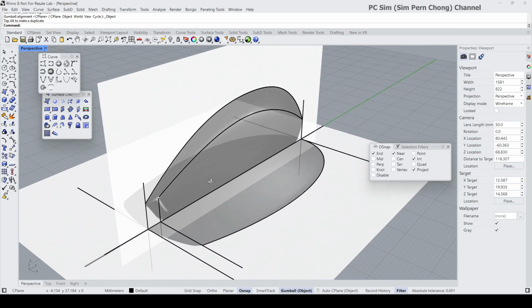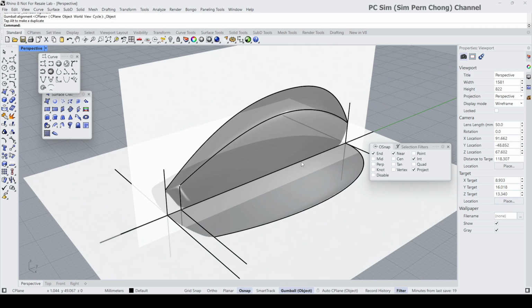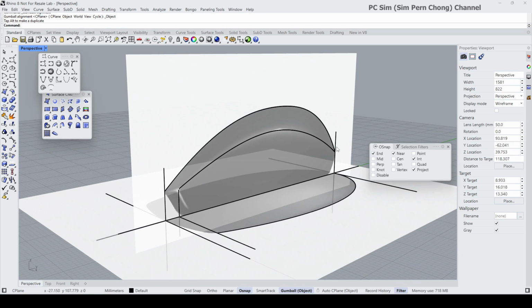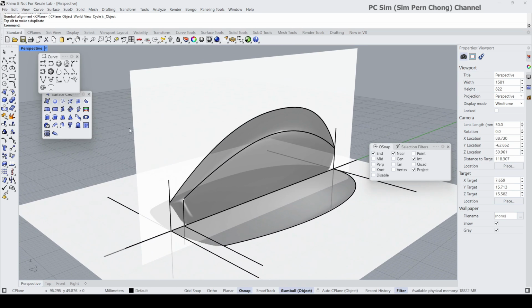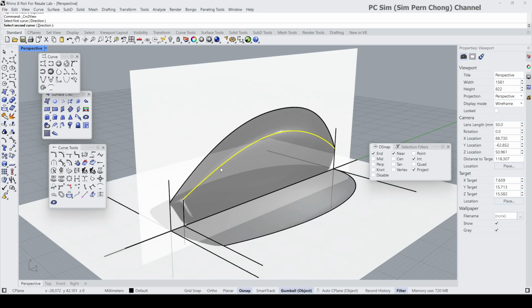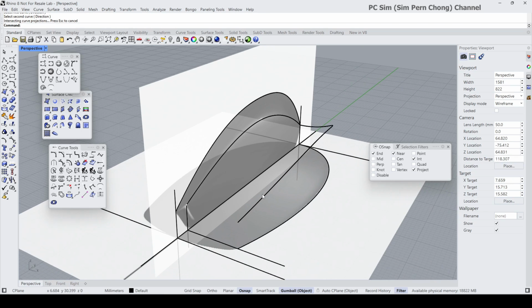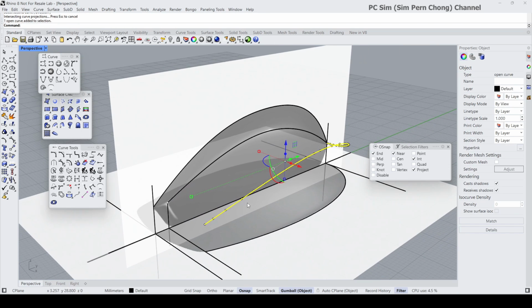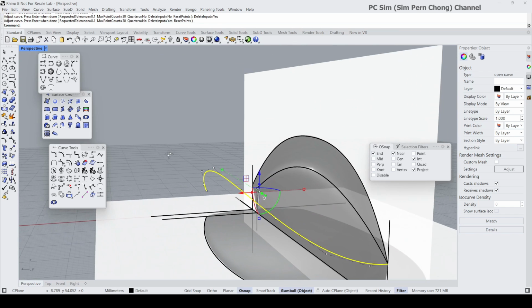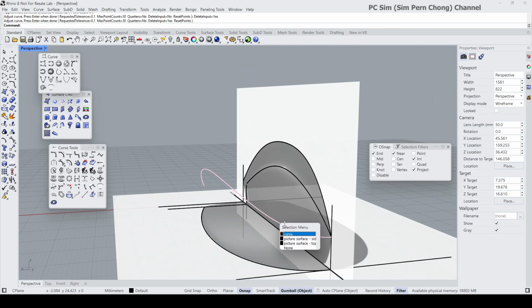The next process is to create this curve in 3D, and that's where we can use a very beautiful command, this one, curve from two views. Awesome. So we have this, and then I'm going to use rebuild curve non-uniform, reduce the control points, delete input. Got something like that, and then let's mirror this to the other side.